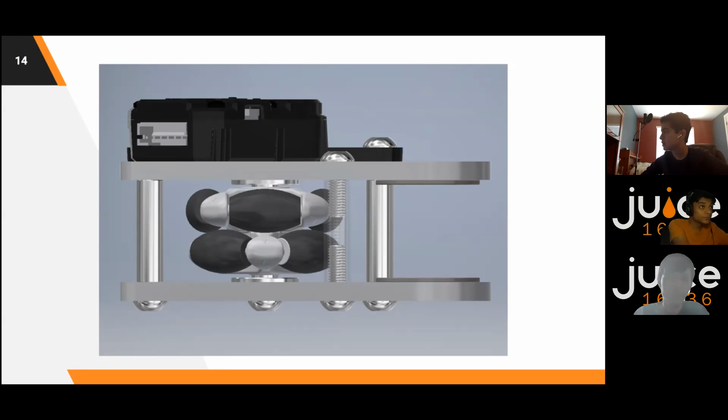Yeah, so then someone asked, could you highlight the differences between PID and dead wheel odometry? So PID is this error correction system, whereas dead wheel odometry is the odometry modules that's showing on the screen right now that actually track the position. So you use the output from the dead wheel odometry system to give an input into the PID loop.